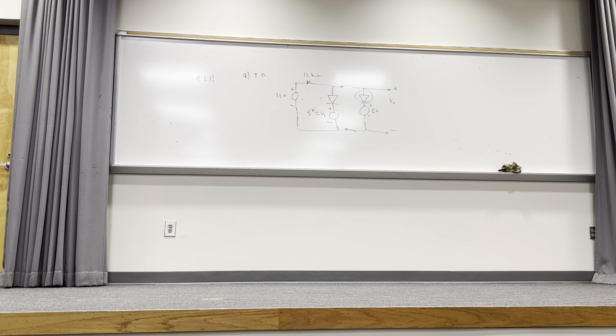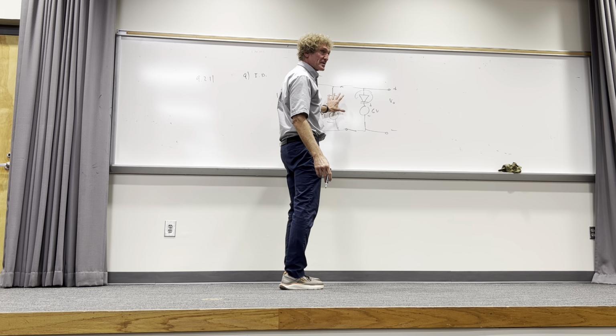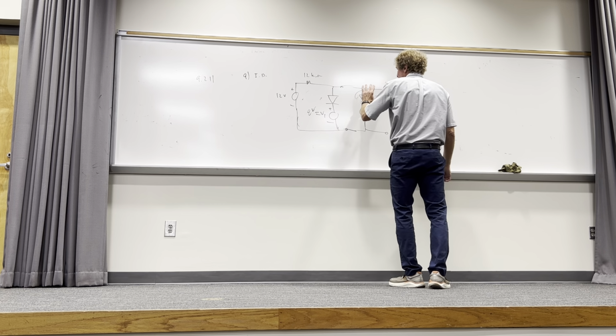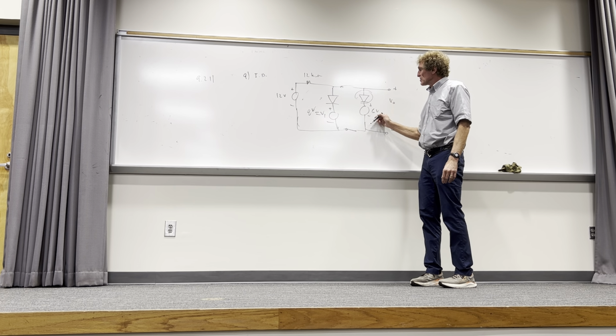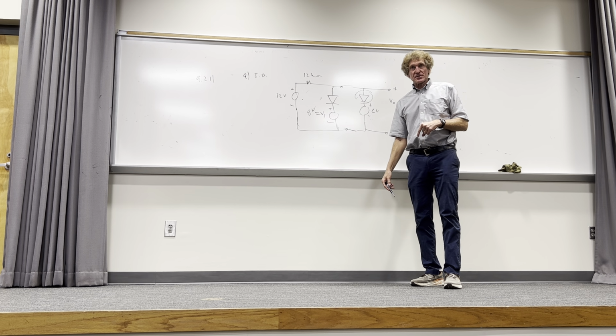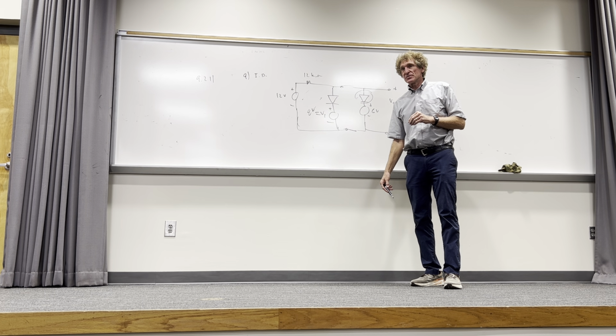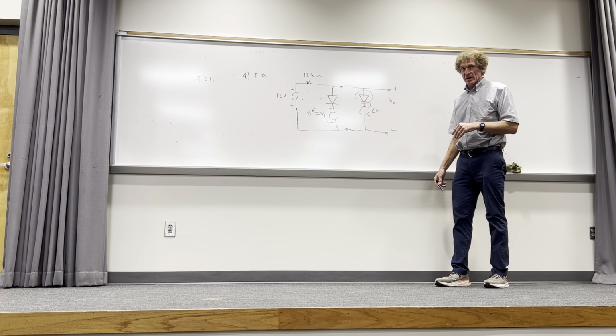Do you see it or not, guys? It has to be based on the same idea we had earlier. If we take this one out, the output would be 6 volts. If we took this one out, the output would be 8 volts. Well, there is no way there can be 8 volts there if only 6 volts is required to turn this diode on. It will be brought down to 6 volts. Do y'all follow me? Has to be. These are good problems. It basically makes you aware of some of the mechanisms for blocking certain circuit paths for current flow. All right, with me?